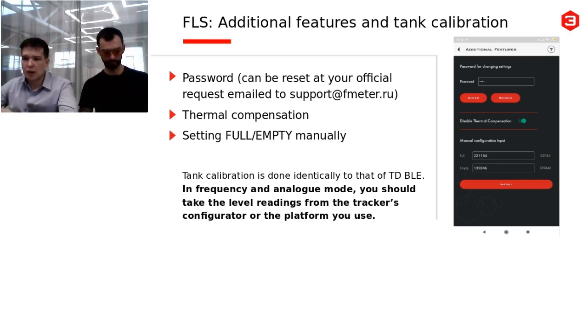Then here we also have thermal compensation. You can also set full and empty manually, in case you have done the calibration before for one tank and now you have to install on an equal tank or the same tank. I mean, almost the same tank. But again, we advise against that because every tank is actually different.